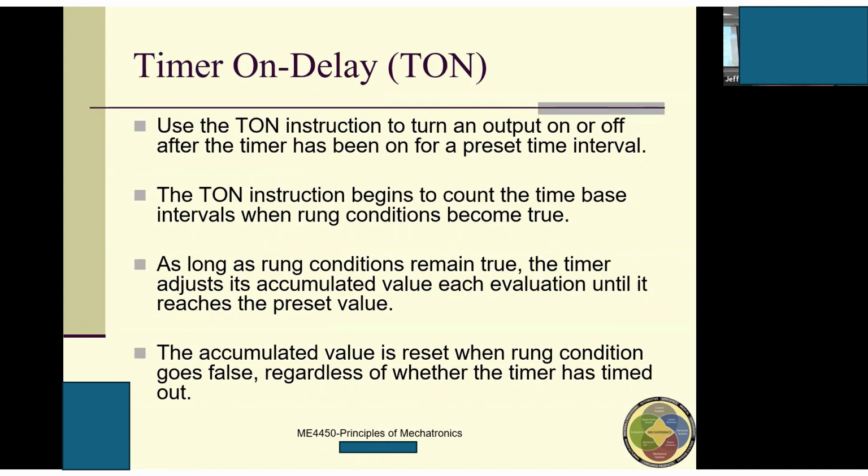And then we talk about the first one, timer on delay, or TON, okay? I want you guys to pay attention to the difference between TON and TOF. Based on my prior teaching experience, some students did not pay attention to the difference. They are different, okay? Even though both of them are timers, how they are triggered is totally different. You use the TON instruction to turn the output on or off after the timer has been on for a preset value interval.